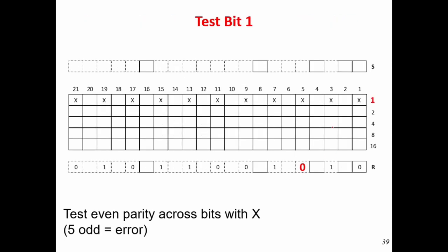So the procedure is like this. Now we are talking about the receiver side. This is similar to the right-hand side of the circles that we already visualized. So the receiver first looks at the first row for this parity, and looks at the information in these marks here and sees how many ones are there.